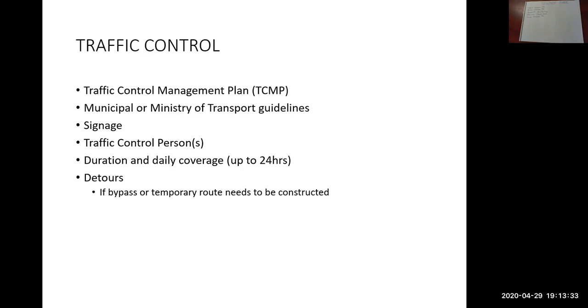So whether it's lane closures, single lane alternating, anytime you need a flagger on a road, or you've got cones on a road, etc., where you're affecting traffic in one way or another, you typically need this traffic management plan. There's companies out there that produce these sorts of things. Again, there's a cost to that, so it needs to be added into your estimate.